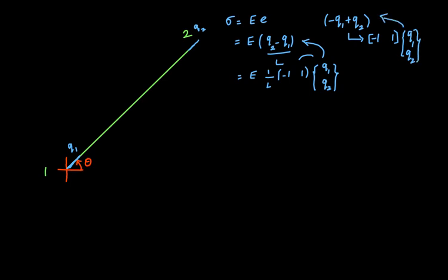Fine. Now this capital E is the stress-strain relationship matrix. It's the D matrix. All right. And this is the strain-displacement matrix, minus 1 by L, 1 by L, including the whole terms. For a one-dimensional element, this is the B matrix, and these are the displacements, the U matrix. All right. So we are ending up with the generic equation for stress, that is D B U. All right. This is a column matrix.